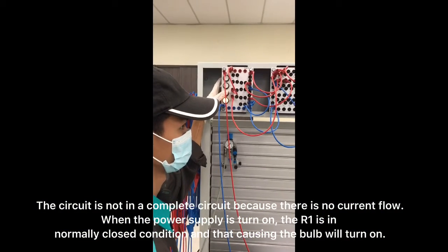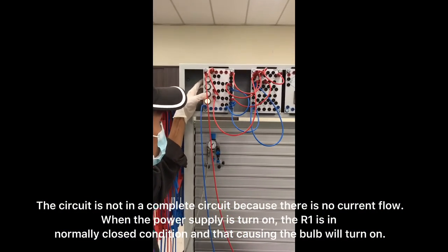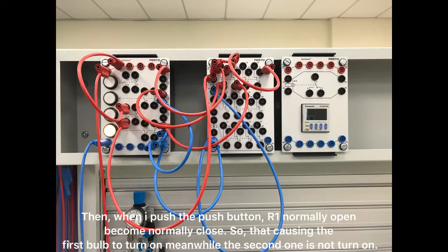For Task 1B, connect the devices as shown in the figure and test the circuit. The circuit is not complete because there is no current flow. When the power supply is turned on, R1 is in the normally closed condition, and that causes the bulb to turn on. Then, when I push the push button, R1 normally open becomes normally closed. So, that causes the first bulb to turn on, while the second one is not turned on.